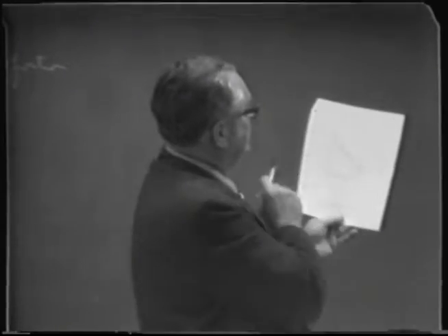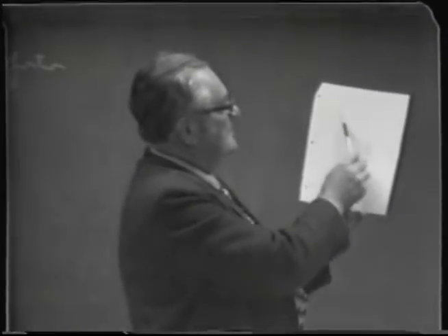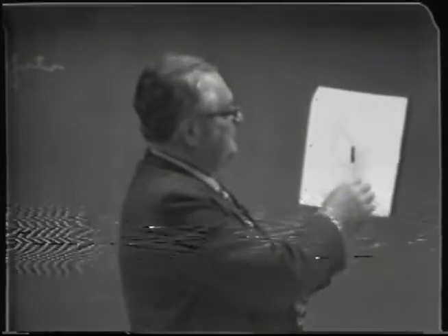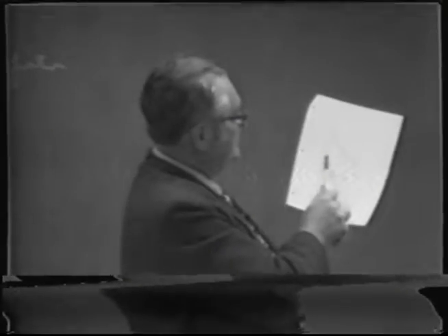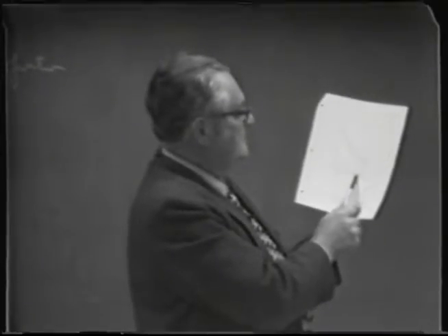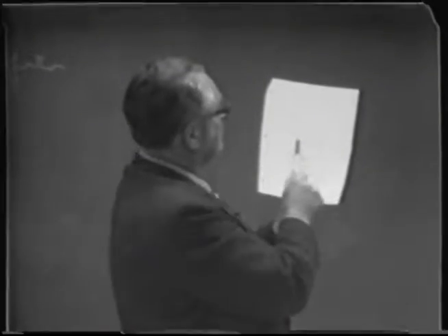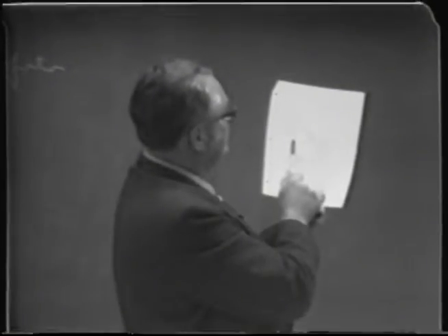I think 10.8 is the figure that was used in plotting the extreme left-hand side of the ethyl alcohol curve. And of course, at different values, you can take the data off and plot it, and this would naturally decline down to a value of 1 when you have the azeotrope at about 95% by volume, 97% by volume. The value for ethyl alcohol comes down to 1, representing the azeotrope.